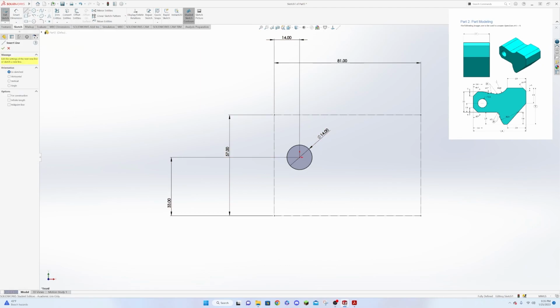So to start off with, we're going to go to our line tool, just our straight line tool. We're going to come over here and we're going to look at the object a little bit, and we're going to start drawing. Now, one thing you want to make sure that you avoid while you're doing this drawing is that Solidworks snaps you to objects so that you get these mates and relations and joins that are handy sometimes, and sometimes that's super useful. Sometimes though, if I was to start my object at the center point of this line and go up, it's going to create a join there for a coincidence for the start point of that line to the center point of this line. And so then that coincidence is going to affect how things move around. And so with this, we kind of wanted to avoid that happening.